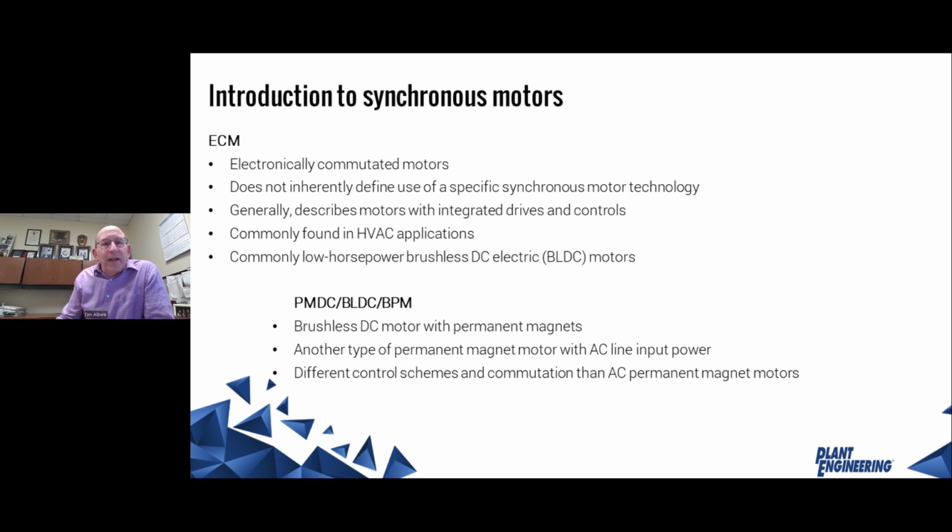Okay, so when you've got an ECM motor, don't think that ECM is a motor technology in and of itself. It's not. It just means that they've taken a synchronous motor of some type, most likely a PMDC or a synchronous reluctance with PM assist, and combined it with a drive. That's what an ECM motor is, and really nothing else.